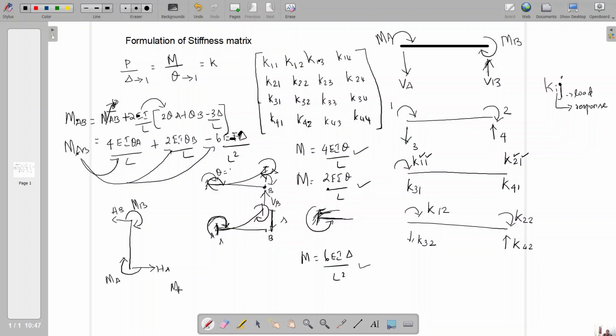So if you take moment at B equal to 0, and you have some height h for this, what is the reaction? You take the moment at this point. First of all, you consider the direction. I am considering MA is positive, this direction is positive. So MA. HA is opposite to this direction, so minus HA. And we need the perpendicular distance to convert HA into a moment, because MA is already a moment value, so there is no need of multiplying the distance. Here HA should be multiplied with the perpendicular distance, HA into h,